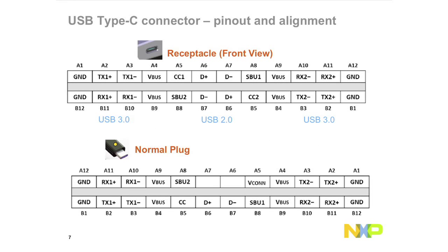Real quick look at the pinout. You can see it is much more complex than your typical USB 2 or USB 3 pinouts. And it also shows you how there is a pin assigned to do everything that I just mentioned. So right in the middle, you see your D+ and D- lanes. That is for your traditional USB 2 support. On either side, you see 2 pairs of high-speed differential signals on each side. Those are your high-speed lanes for sending USB 3 data.